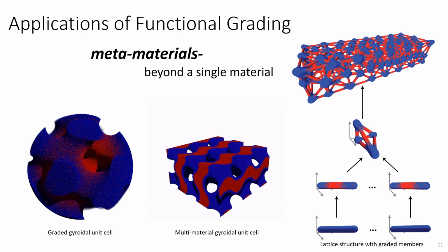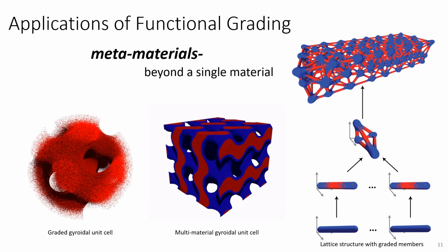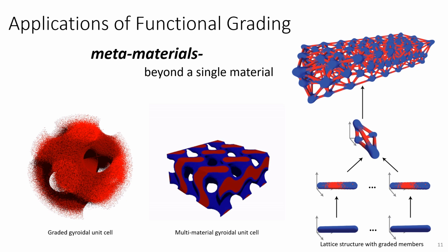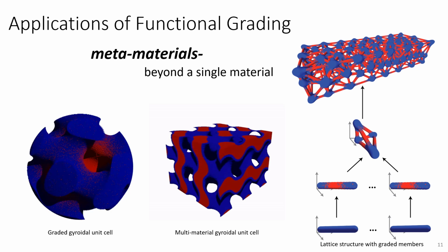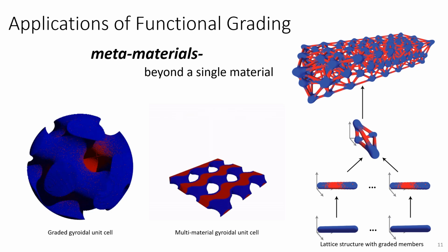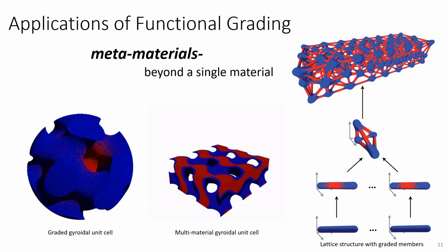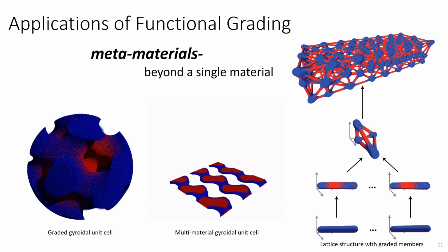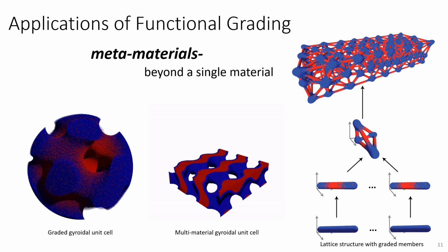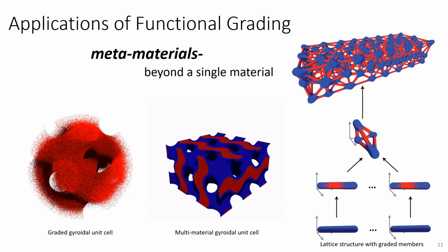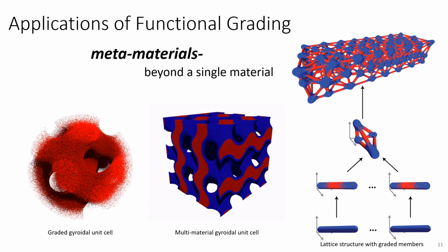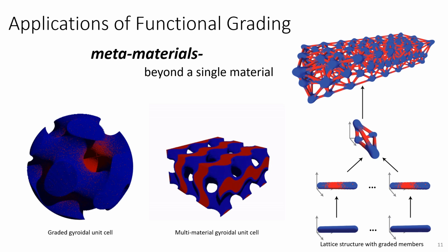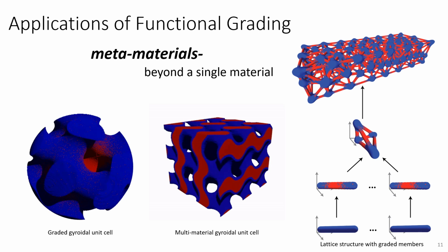And then finally, this is really great for lattice structures. OpenVCAD has the ability to define lattice structures, both strut-based as well as other unit cell lattices, and tile those across space. But what's really awesome is we can use these multi-material nodes anywhere in our trees, right? In the case of this lattice structure, we can define our individual struts. We can grade uniquely across each one of them, or uniformly across each one of them, and then composite them into one big structure.